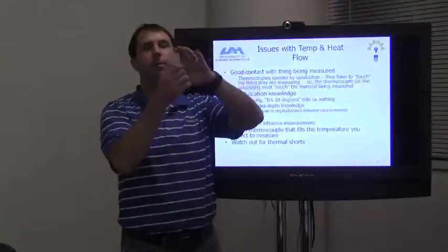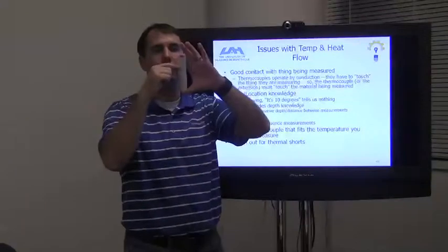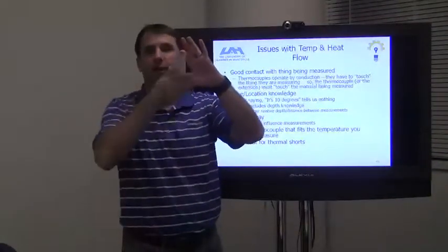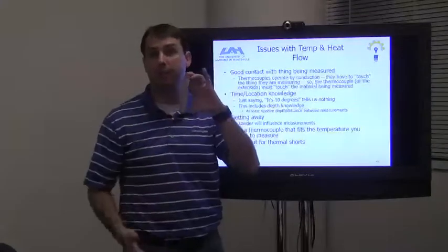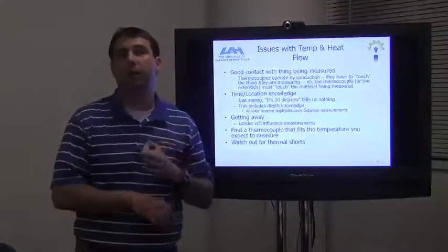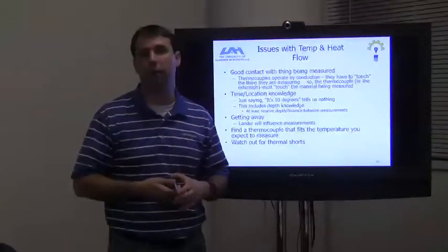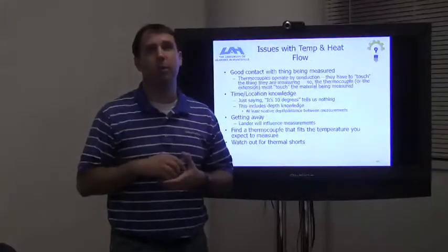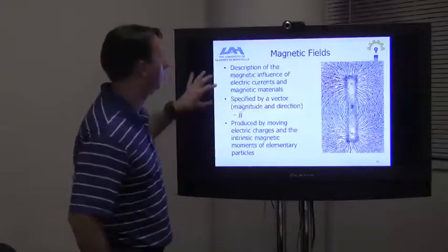Let's just say this is my penetrator, and I put thermocouples along the walls of this penetrator, and the outside of the penetrator is made of metal. The entire outside of the penetrator is going to be the same temperature after a while, because metal conducts heat. And so that's a thermal short. Basically, you've created a short across the entire penetrator because it's a metal and because metal conducts heat. So you want to watch out for thermal shorts. We'll talk about that as your designs mature.